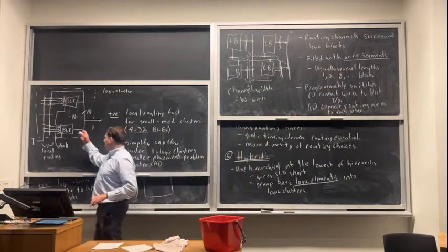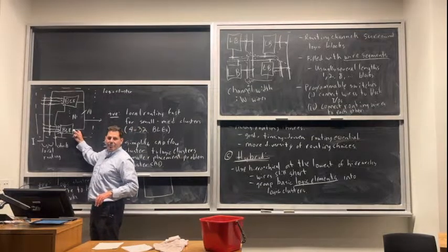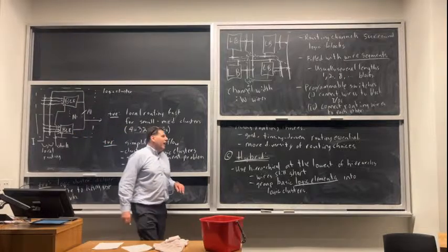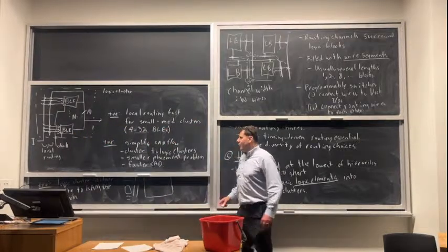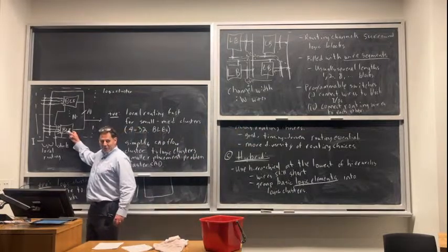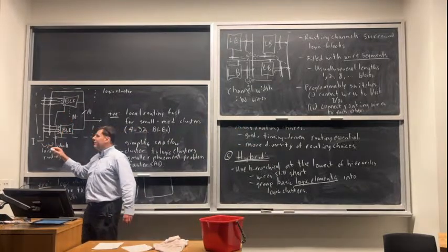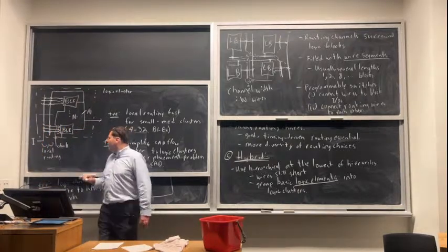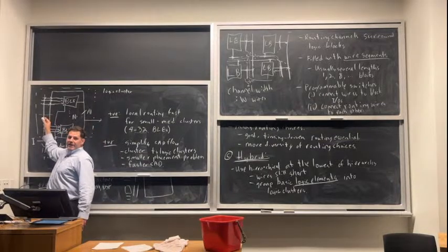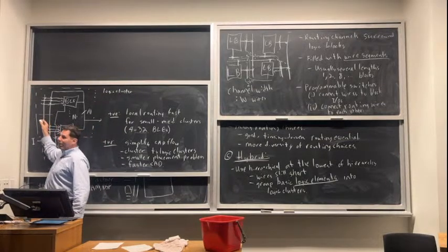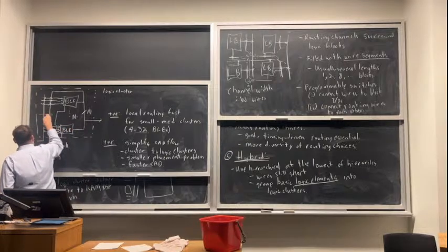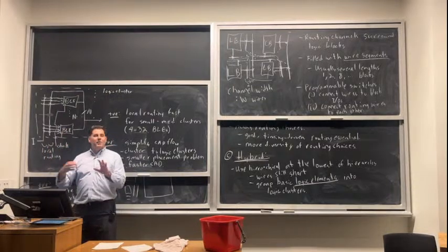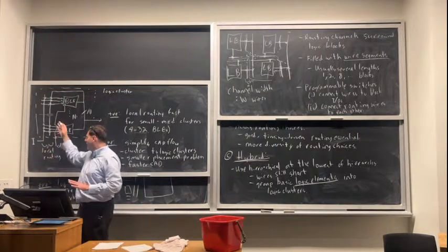Now Xilinx uses little hierarchical FPGAs like Altera did. So they've moved to a hybrid architecture. For many years, Altera used exactly this. It was like one level of hierarchy. The local routing was very easy to understand, et cetera. And in their latest generation, Agilex, they've said, well, some of these wires in 10 nanometers and 7 nanometers are starting to get a bit slow. So they've started making some of these wires only go half the height and some go the full height. So it's like a two-level hierarchy kind of. They've made their hierarchical FPGA inside the cluster a bit more complicated.